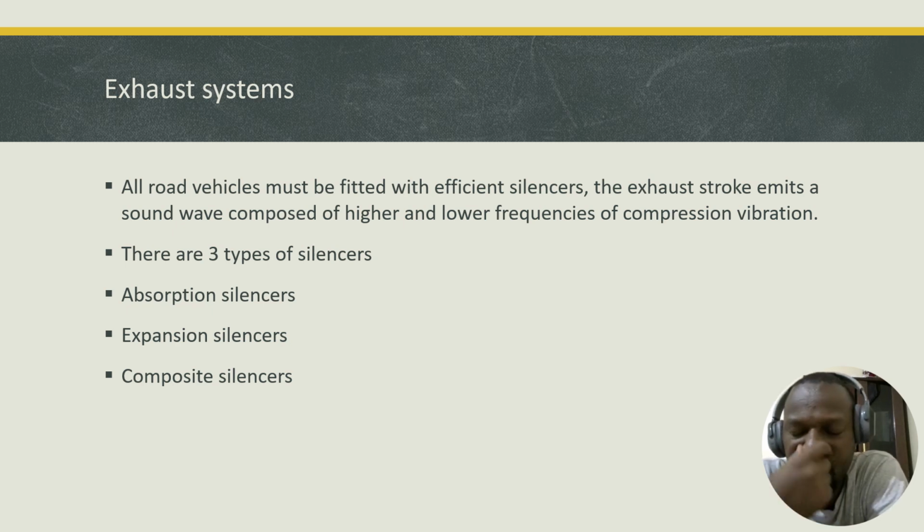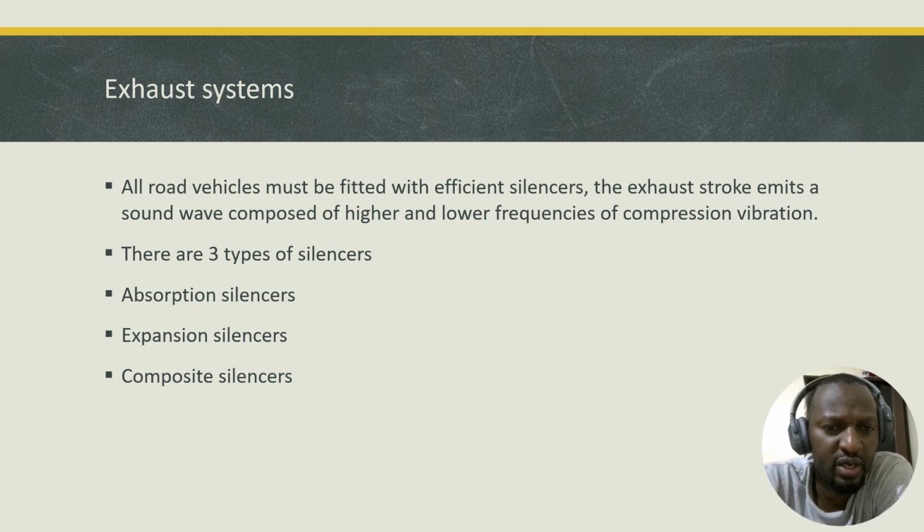If you were to put a straight pipe, there is also the problem that the air flowing out of the engine would flow too fast and cause the engine to consume more fuel. And how is that possible? The exhaust system should ideally create a back pressure so that as the air is leaving the engine, the inertia generated by the air leaving the engine is dampened by the resistance, so that the fresh charge coming in cannot find its way out during overlap and escape with some fuel particles. That is why a vehicle with a broken exhaust will lose power and also consume more fuel.